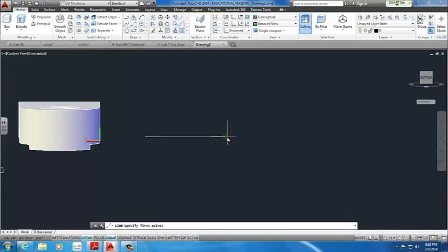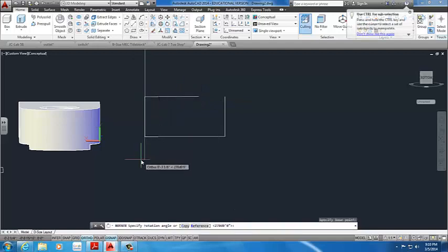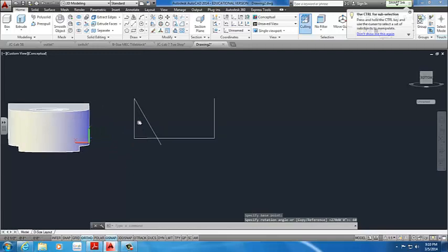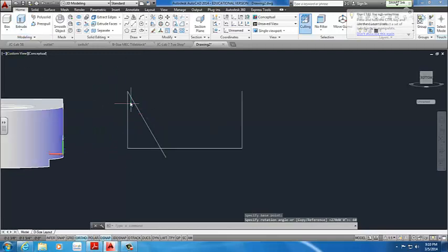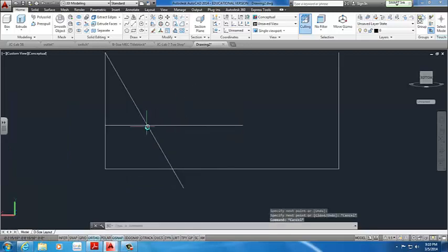So we draw a line 2 inches high. You can do that on both sides as is. And now the situation, we have a 60-degree angle. So what we want to do is draw a line. I'm going to rotate it around to 60 degrees. Like so. And it ends at a distance of a 1.25. So we go down ortho 1.25 and across, and that gives us our endpoint for this sharp angle.